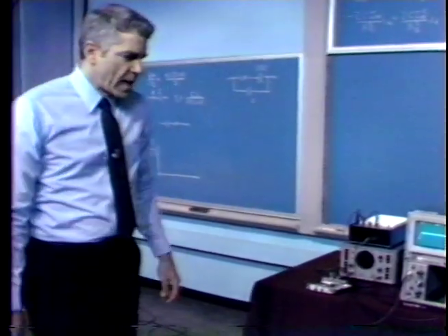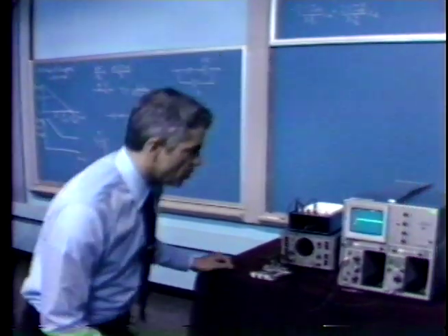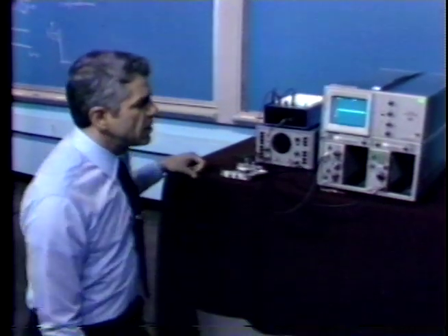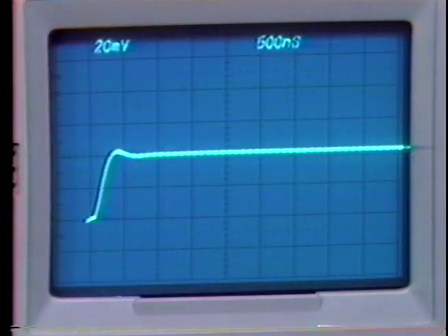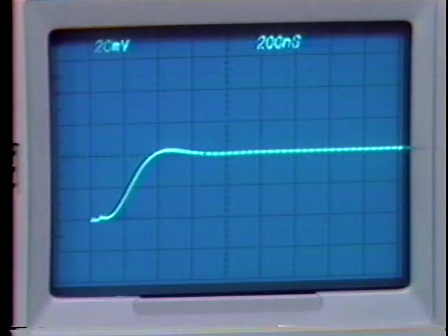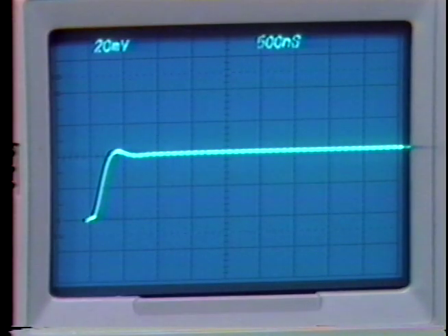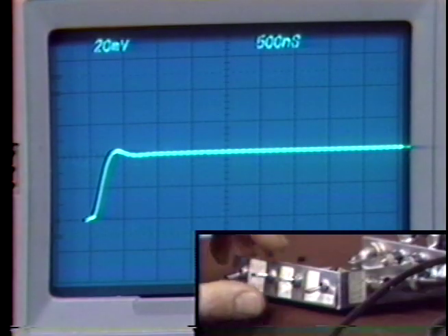And at present we have the amplifier compensated for single pole operation, and we see the resultant step response on the oscilloscope. We're using about a 20 picofarad capacitor with this particular amplifier, which is the same one we used in the last series of demonstrations. We get a 10 to 90% rise time of about 200 nanoseconds with that value for single pole compensation, implying that the crossover frequency for this configuration is somewhere in the order of 2 megahertz. And this is operating without any capacitive load.